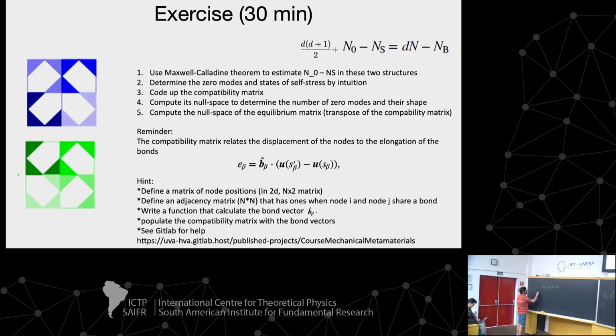So here what you would do is write epsilon 1, epsilon 2, epsilon 3 equals the matrix times U. And then you know that, for instance, the strain in the spring, epsilon 1, is due to a displacement of the node U0, right? So here you would have a 1. Positive displacement leads to a -1, right? Then you have 0, 0, 0.